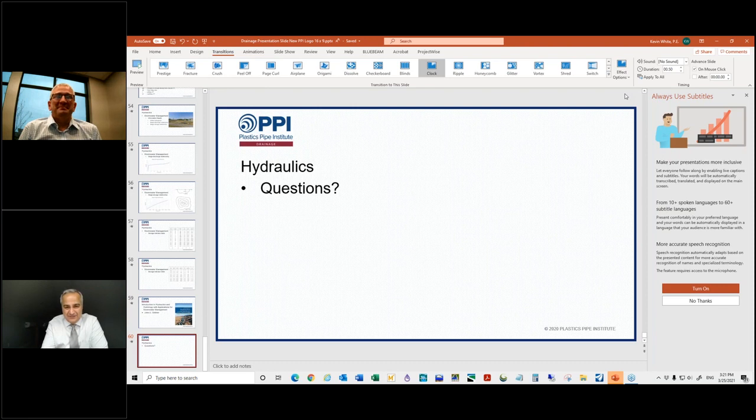And please, if you have other questions, you can type them in. But we had a question back on figuring these storm frequencies. I think that's kind of the place where everybody starts this process, and it's one of those things: if you don't feel like you're starting in the right place, then how do you trust where you're ending up? But we talked about 10-year events. What about a situation where you're being asked to do a 10% exceedance storm for determining intensity? What do you think about that method of determining your design storm, a 10% exceedance storm rather than a probability event?